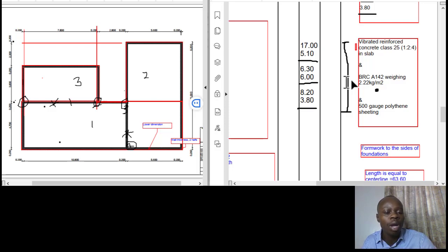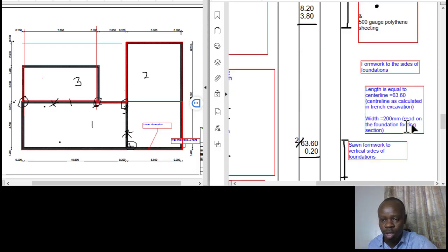So you simply take the total area that you've already calculated, that is for the slab, and then you now adjust it by subtracting the areas for the walls, because you need the hardcore just within the walls. Okay, so that is an easier approach to use for you to get now the area for the hardcore. So that is what we need to do right now.